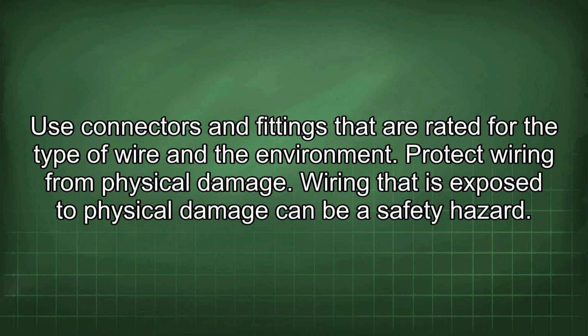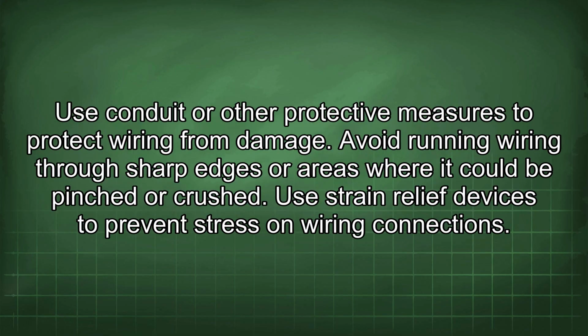Protect wiring from physical damage. Wiring that is exposed to physical damage can be a safety hazard. Use conduit or other protective measures to protect wiring from damage. Avoid running wiring through sharp edges or areas where it could be pinched or crushed.